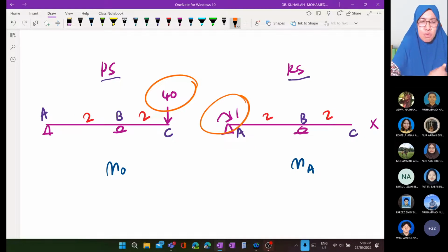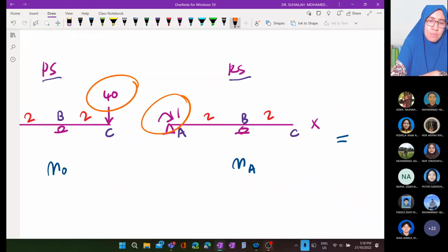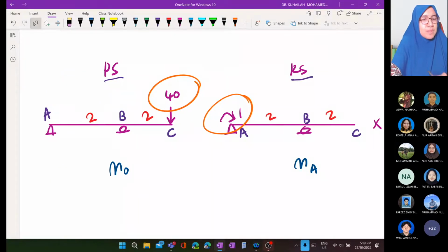So this is the moment. We apply a moment at A as an applied moment, not as a fixed support, but we apply a unit moment, a unit value of MA. We divide by MA because we want to analyze due to a unit value. So there are two systems: one is the primary system and another one is the redundant system.